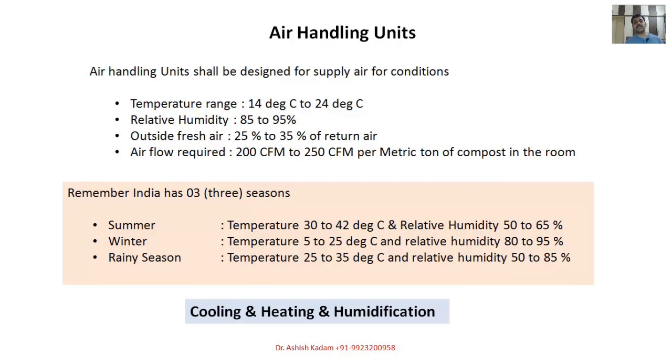But naturally their investment is very small, they are very much prone to nature, or they have understood nature, or sometimes they provide some other heating arrangement on a few farms in northern India. If you have temperatures lower than 15 degrees, we need to have a heating arrangement, and that is why we always recommend hot water coils for maintaining the right temperatures.